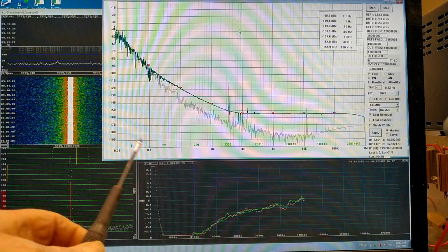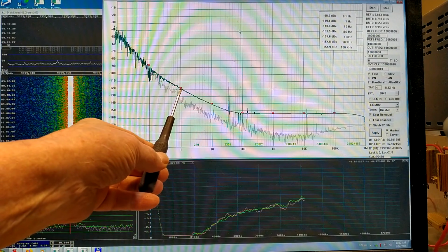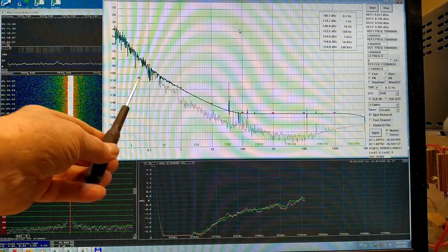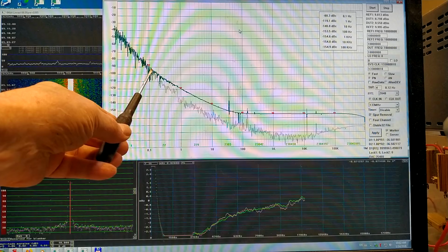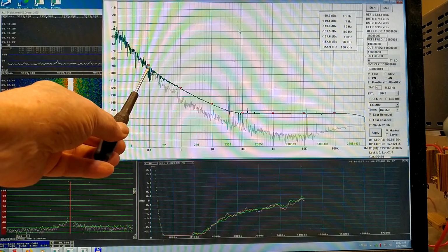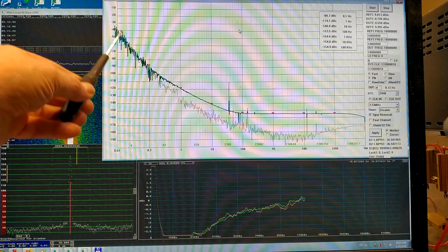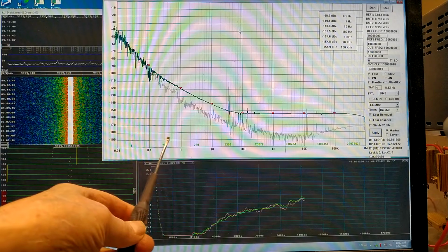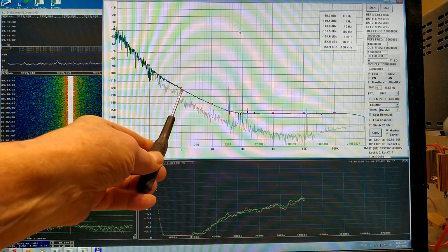The sideband noise at 1 Hertz offset is minus 119 or something, and at 0.1 it is about, hard to say, minus 93 perhaps. It has not converged properly, and here it is far from convergent. So I need an improvement in the order of 10 decibels at least.